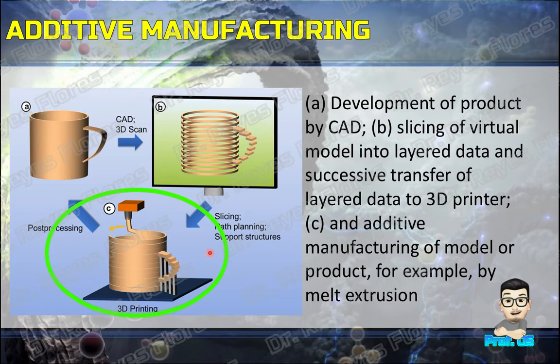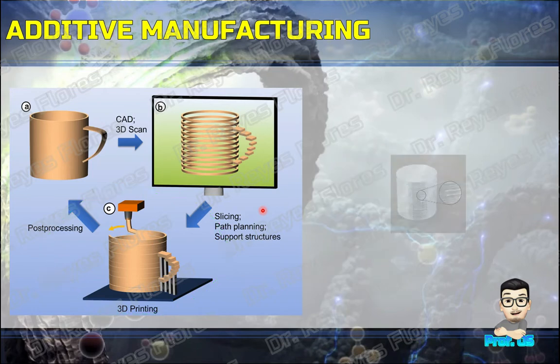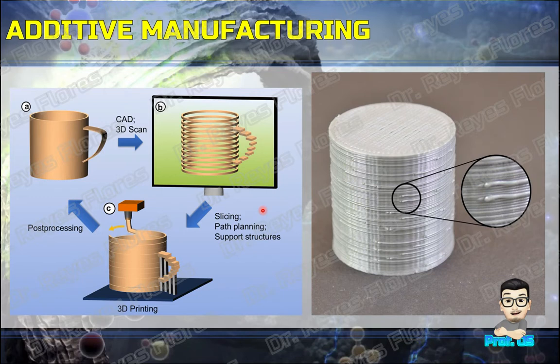For practical purposes, this type of computer-aided manufacturing is normally performed layer by layer, with typical layer thickness ranging from 15 to 500 micrometers. When the layer thickness is below 50 micrometers, the naked eye will in most cases not be able to recognize the stair steps associated with a layer manufacturing approach.